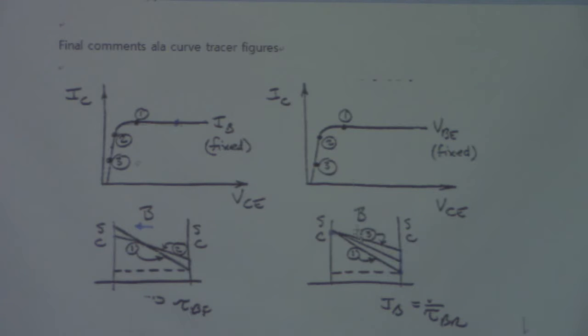But after it is saturated, the charge has to show something like this, number 1, which is the same as this, after the saturation. But before the saturation, now the slope is going to get slower, and the way to show the slope slow is to have different values at this space charge region, and this space charge region point has to be fixed because we fixed the base emitter voltage.